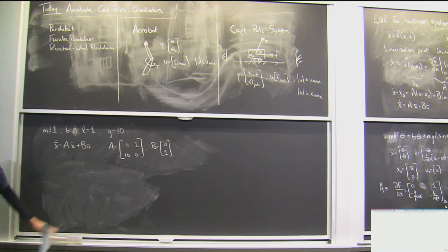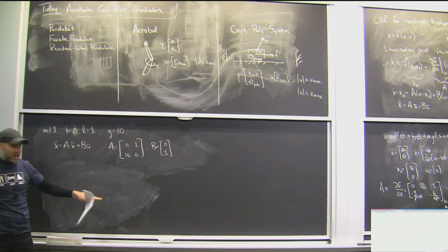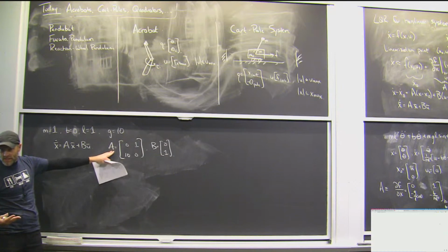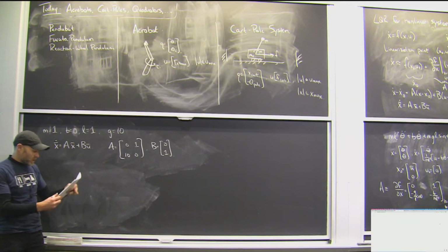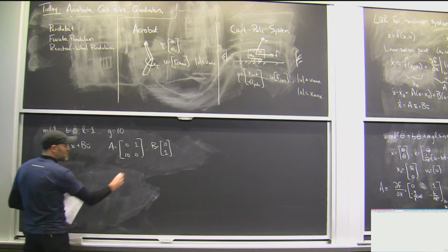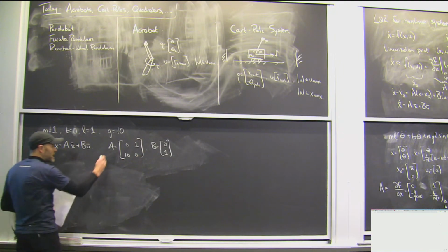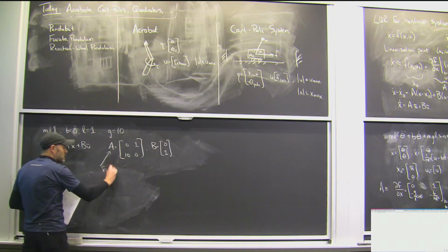Okay, so for two-dimensional linear systems, you can do the same graphical analysis we did before, but you can use the eigenvalues and eigenvectors of A to understand the two-dimensional plot. Okay, so if I were to try to plot what's the dynamics of this with u equals 0 for a minute, that means that's going to be x bar dot equals A x bar.